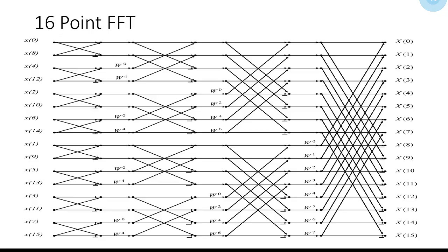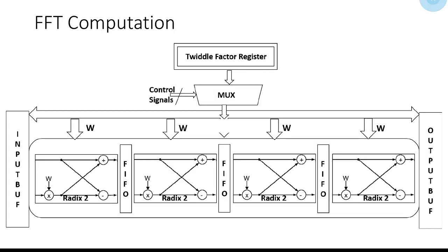The architecture chooses decimation-in-time-based 16-point FFT architecture, which equalizes the first stage hardware complexity by merging with the floating point conversion module and the last stage with absolute computation. A single butterfly along with FIFO and FIFO control is reused 4 times to compute the 16-point FFT's 4 stages from input to output.